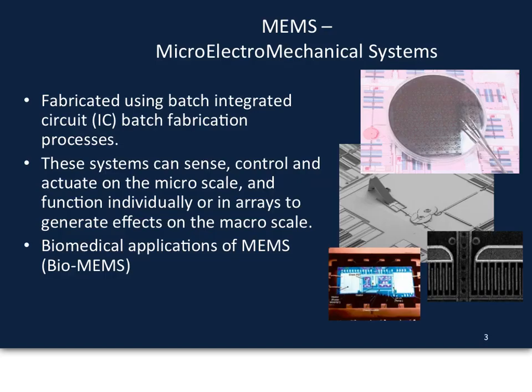The acronym MEMS stands for Microelectromechanical Systems, and these are devices that are fabricated using the same kinds of technologies that are used in integrated circuit fabrication. So they essentially are a descendant of that, a new application of things like deposition onto substrates, patterning by photolithography, and etching, etc.